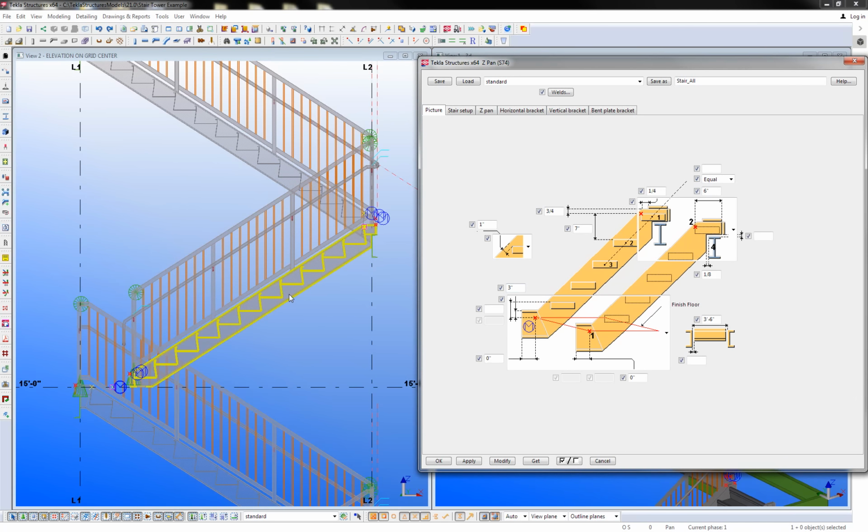So I'm going to go ahead and adjust some properties before I delete it, now that I've got this dialog box open. So I'm going to go ahead and change that again to be extending out. I don't know what these dimensions are going to be just yet. I do already have this stair laid out, but I want to show you, just in case you don't have it laid out yet, kind of a poor man's way to check and adjust as required to get the proper rise and run for your treads.